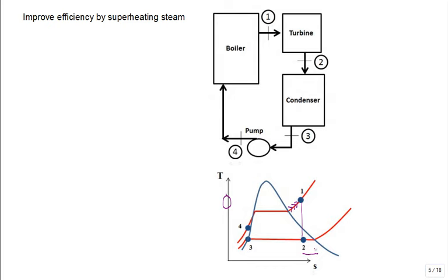If you have a two-phase mixture of some gas with some particulate in it, typically you make it turn, and the inertia of the solid particle keeps it going, and it goes out to the wall and strikes the wall and is collected. Take a look at different ways to separate out gases that have some entrained solids, or liquids that have some entrained material that has higher density and little particles.